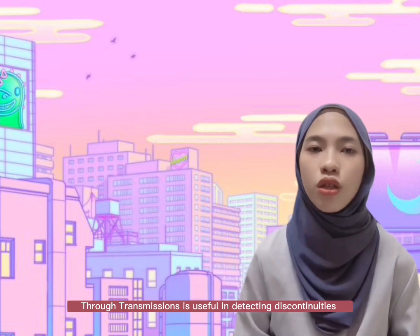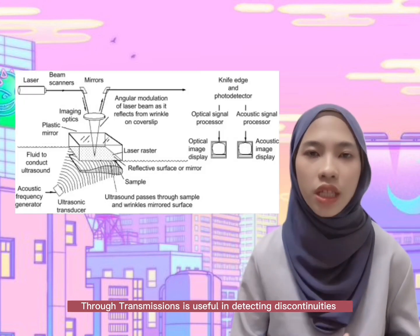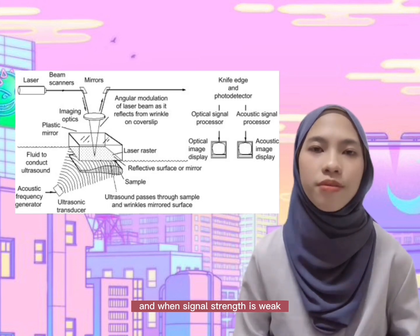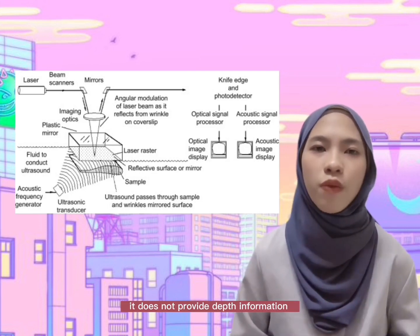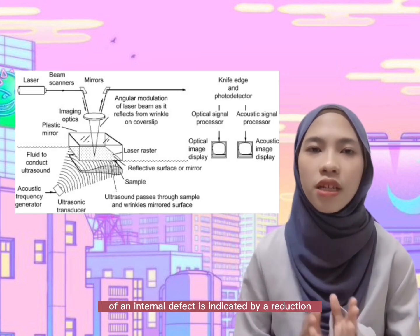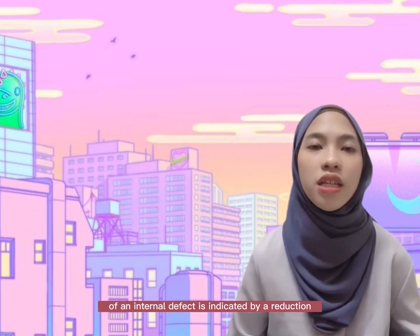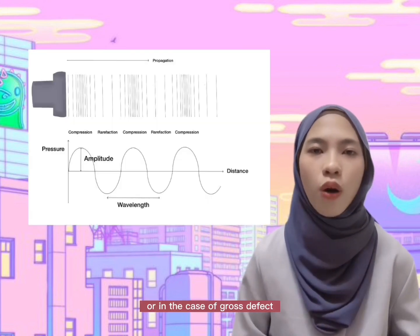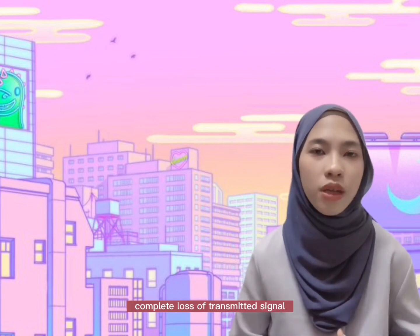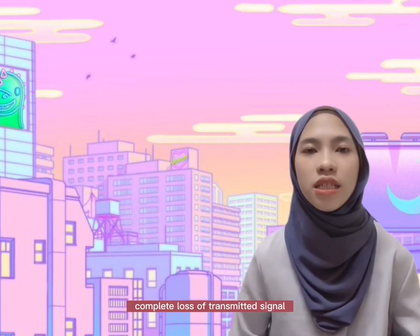Through transmission is useful in detecting discontinuities that do not reflect well, and when signal strength is weak. It does not provide depth information, but in this method, the presence of an internal defect is indicated by the reduction in signal amplitude, or in the case of a gross defect, complete loss of the transmitted signal.